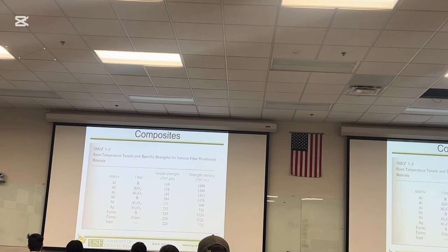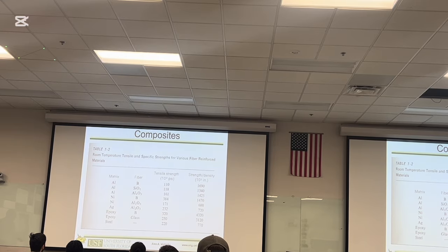So composites, I did my master's thesis on the first system of aluminum matrix and boron fiber. Boron is very brittle, but in the end there was material, pipes, made from aluminum, so they have the density of aluminum but the strength of steel. Super expensive, but that's a construction element of a satellite system. Aluminum matrix boron composite. Or a shell of a rocket, for that matter.